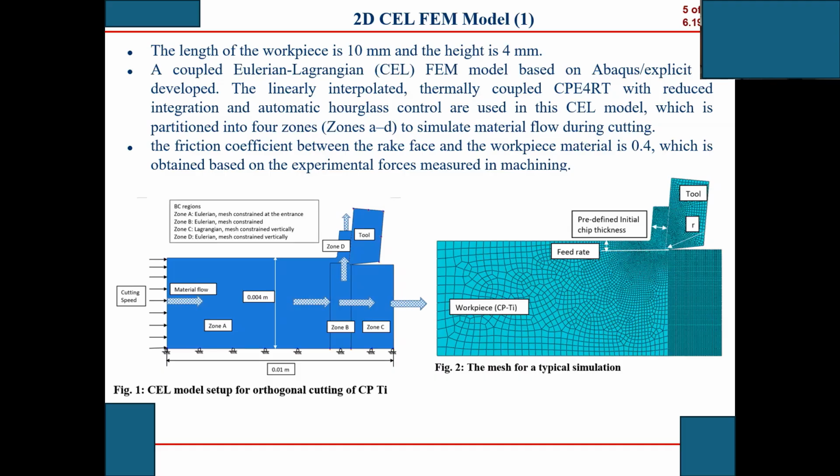Look at this one, this machining. Machining is high speed. Abaqus/Standard is for the static problem, so for this one we use Abaqus/Explicit.